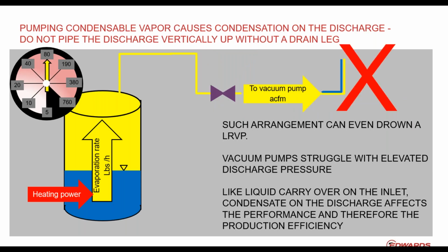And in this slide, it's basically just progressing the same effect to the discharge. So imagine you have a reaction going all through the vapor state. Your vacuum pump handles everything that comes in the vapor state and discharges it to the discharge. And at that state, you're basically on the discharge, standard conditions, atmospheric pressure. Typically what was a vapor under vacuum is now turning into a liquid again. So it's condensing. So it's very common that your discharge line is turned into a condenser.